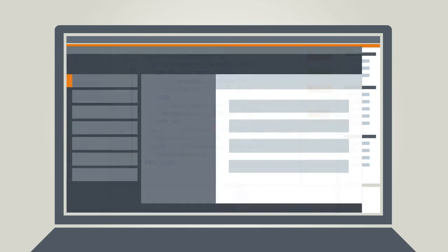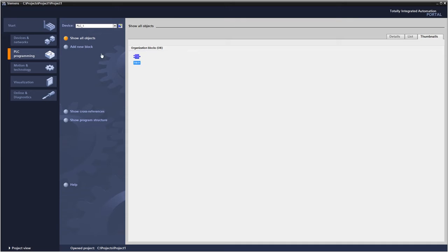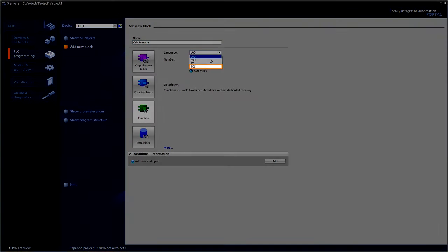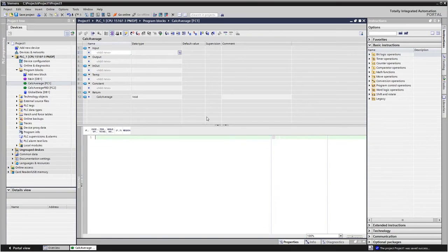So, what does that look like in the TIA portal? Let us take a look at it, using programming with SCL language elements as an example. Let us say you want to calculate the arithmetic mean of the last current values. To do so, you first create an SCL block, for example, a function, or FC for short.